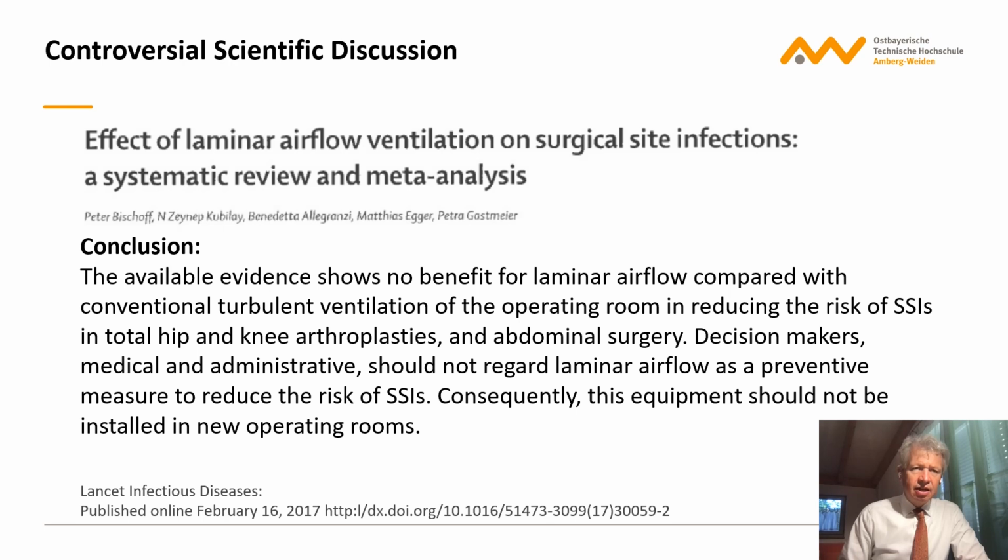Nevertheless, there still is a highly controversial scientific discussion on what effects especially laminar airflow technology has on surgical site infections. In conclusion today, the available evidence doesn't show benefits for laminar airflow compared with turbulent mixing ventilation in reducing the risk of surgical site infections in total hip and knee arthroplasties as well as abdominal surgery.